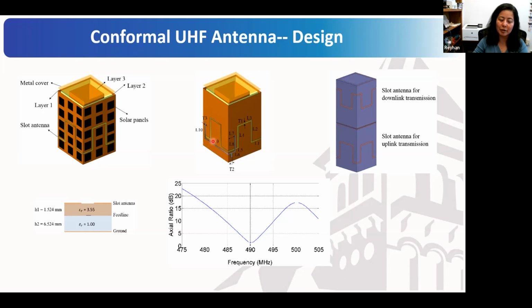Of course, if our uplink and downlink are very close, then one set is enough. For this particular project, this one antenna doesn't have enough bandwidth for uplink and downlink, and therefore we made uplink here, downlink here. Since they are both UHF, as you can imagine, we put them very close on a 3U CubeSat. They will couple, they will lock into a new frequency. To solve that, we inserted the metallic plane in between the two cubes, which makes total sense because that's very easy to do, and also that helps to isolate some electronics as well.